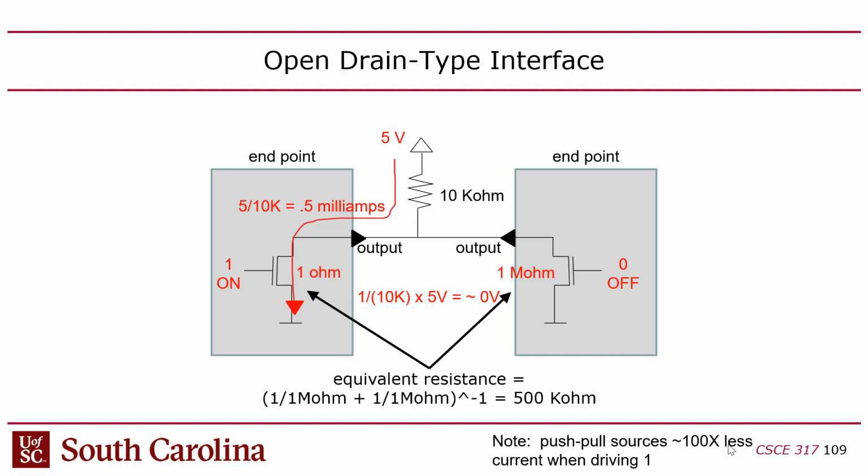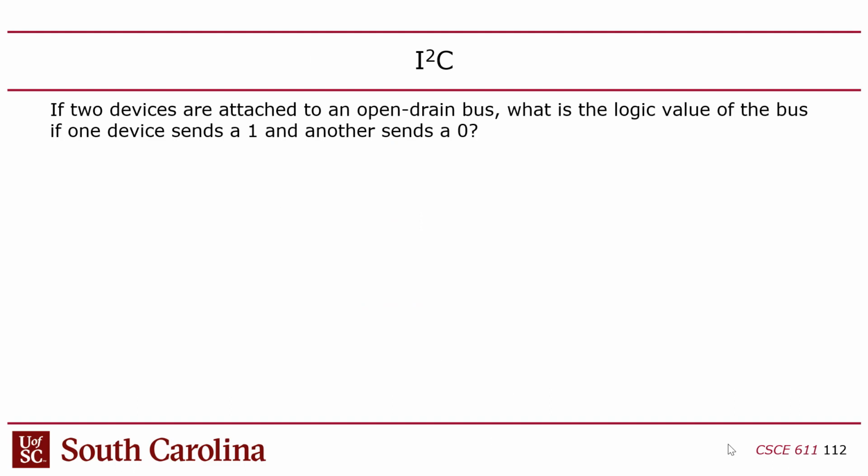I've never designed one, but let's just assume for I2C that there is a way to detect a conflict. And if there is a conflict, no biggie, no big deal. If there's a conflict with push-pull and you don't have the tri-states turned on, or if you have 2 connections that are both tri-state on, and you're trying to send a 1 and a 0, then you can have a short circuit.